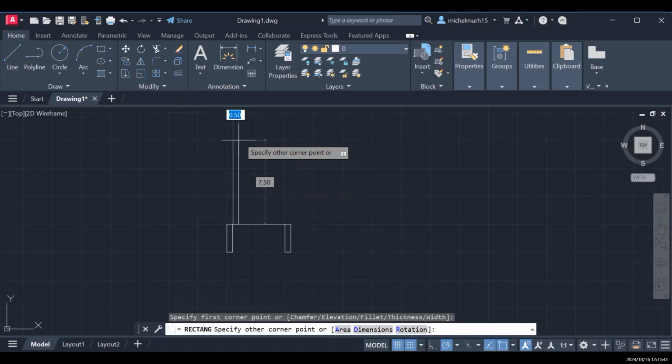For the purpose of the beauty of the design, I'm gonna make it 0.5 thickness, and I can modify the height anytime. I'm just showing the process of designing a window and a door. So from here I can take 0.5 thickness, the one in blue, and if I press tab I can modify the height.